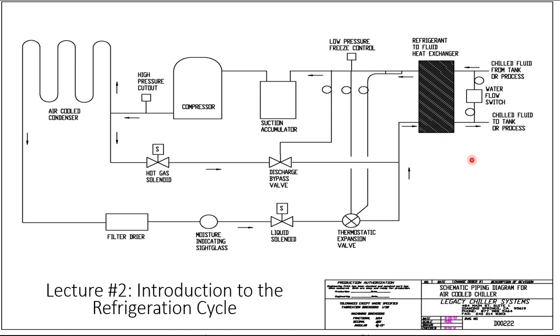We're going to start back at our compressor, and cover the state of the refrigerant when it leaves the compressor. A compressor does just what the name says. It compresses. So on the outlet of the compressor, you're going to have a high pressure gas.